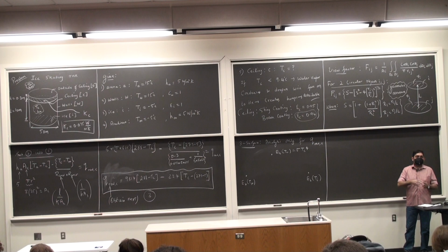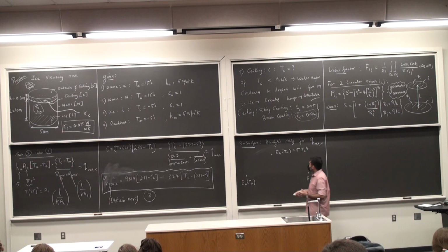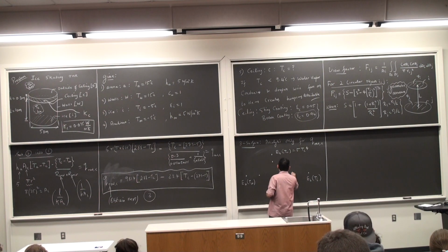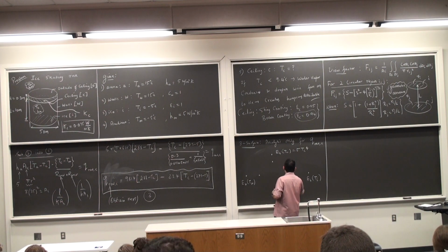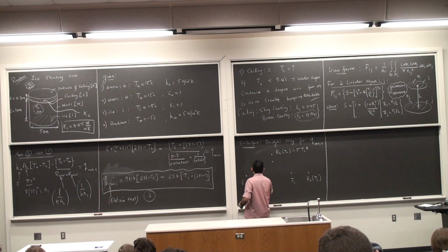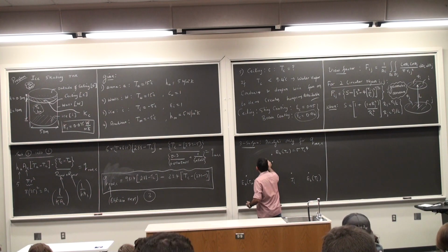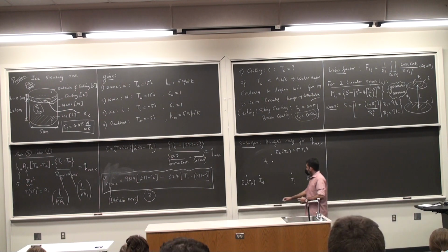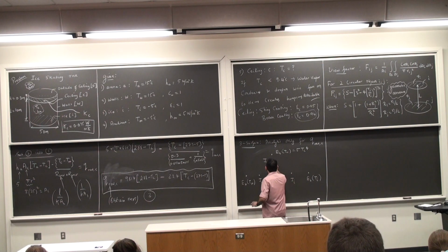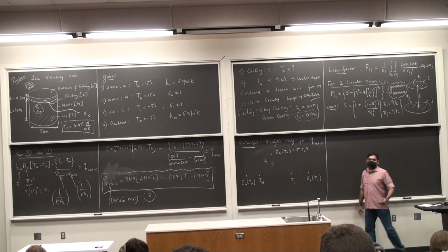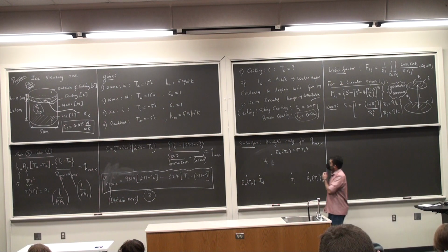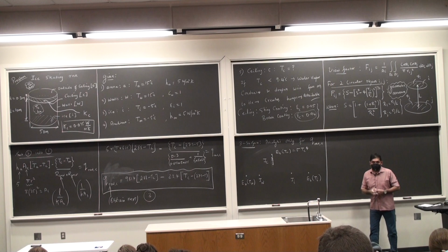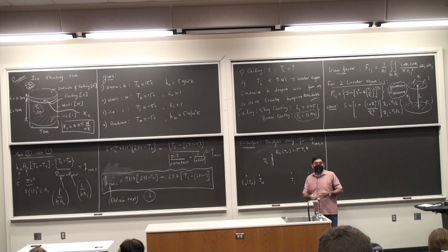Okay, then next come the three radiosity nodes, each below, one here, one next to it, one next to it. So this is J ice, this is J wall, Jc. Okay, and I can push this a little below. Then you join each of them through the resistances. Surface resistances between the fundamental and the secondary nodes. Then the geometric resistances between the radiosity nodes.